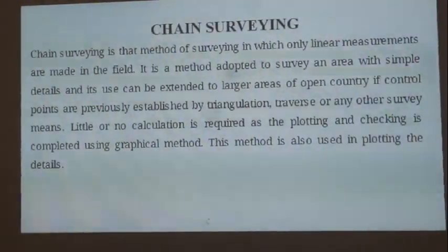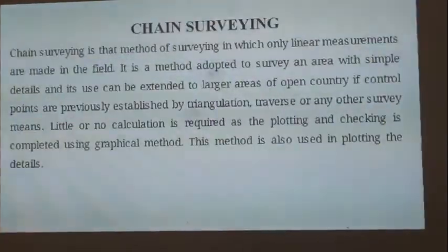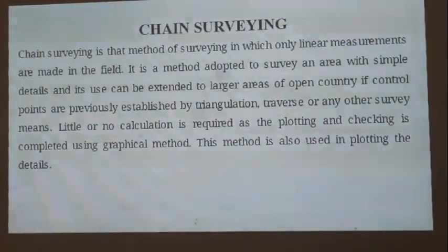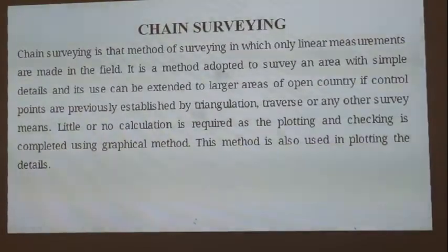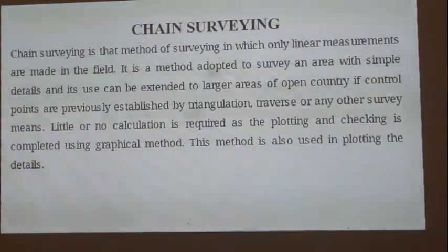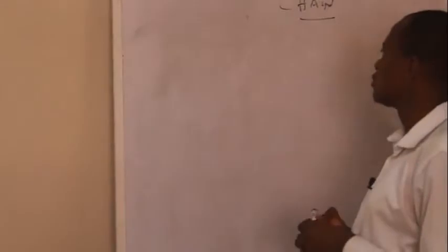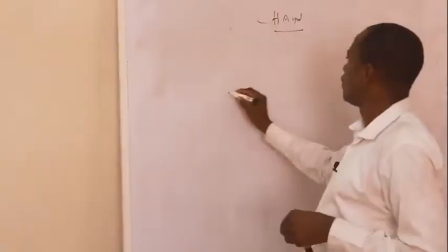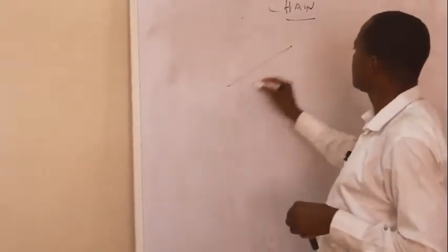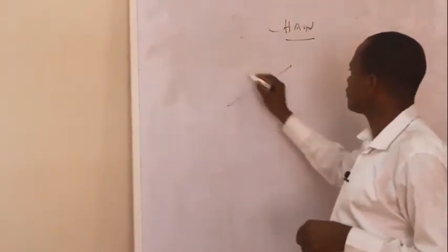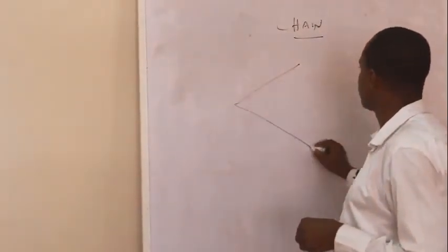And today you can still carry out only linear measurement, and with that you can fix position. Remember when we were touching various means of describing positions, we can carry out purely linear, and we can carry out a mixture of the two. Remember, we want to fix a point. We want to fix another point.